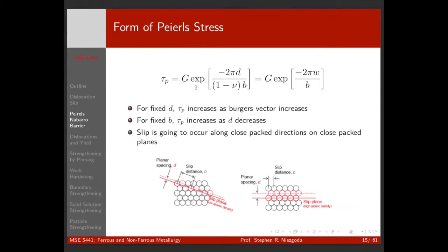That basically says that the higher the elastic stiffness of your material, the higher the yield strength is also. Right? So there's that connection that comes out. And that the wider your interplanar spacing is, the lower your Peierls stress is going to be, the lower your yield stress is, and that the bigger your Burgers vector,